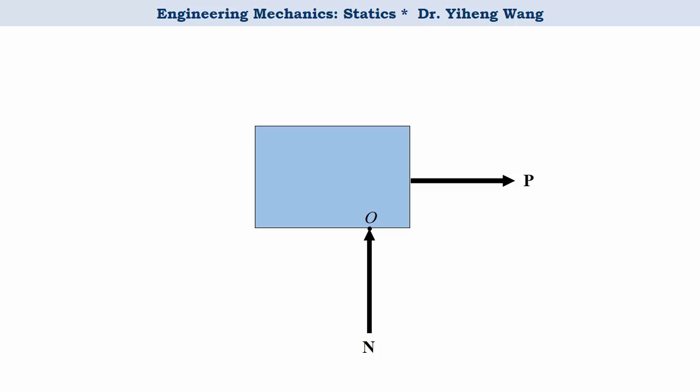And we can do the same thing and summarize all the horizontal component forces and replace them with a concentrated force F. We don't know for sure exactly where we should position this F force, but that's less important. We know this force must act between the two contacting surfaces, tangential to both surfaces, which is good enough for now. And lastly, let's add the weight force acting at the weight center of the body. And now we have completed the free body diagram of this crate.